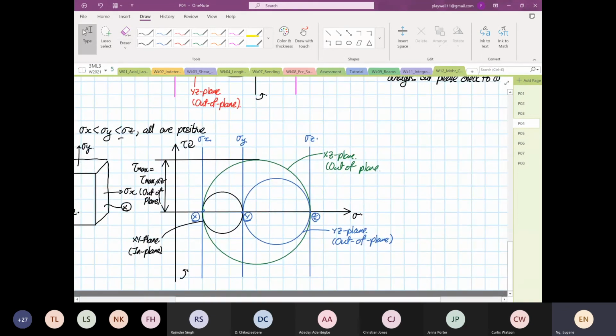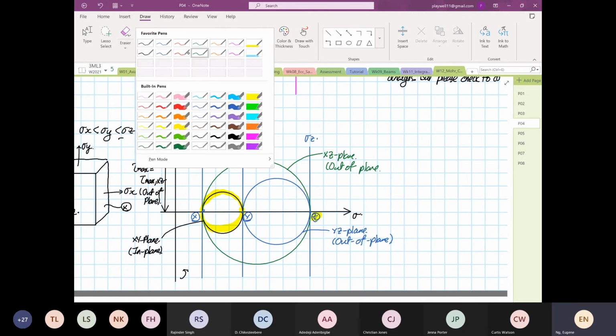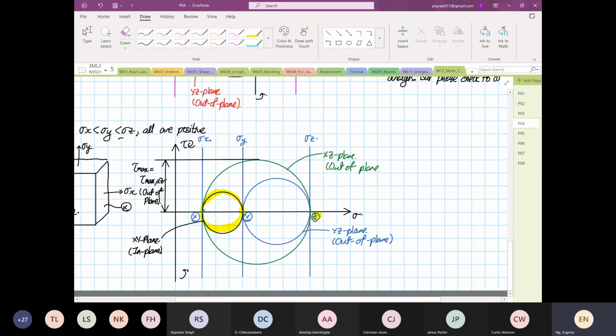Imagine if you only use 2D Mohr circle, and then you call on the principal stress. In fact, Z is your much higher one, and you are done. The material will fail in tension, in shear, in any way you can. It's going to be a catastrophic failure.